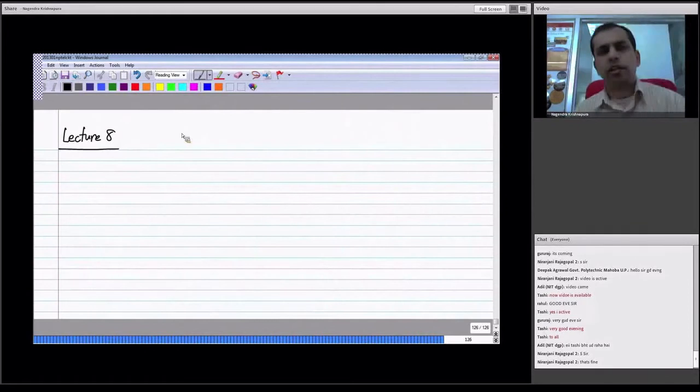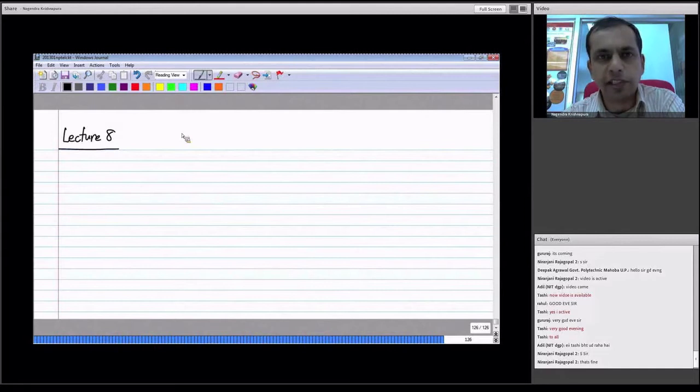This is lecture 8. In the previous lecture, we looked at nodal analysis, how to do nodal analysis when you have a circuit with current sources and resistors. That was the easiest case. And we extended that to when we have voltage sources. In that case, if you are doing hand analysis, you can use a super node. If you are trying to set up the equations for a computer, you can set the current through the voltage source as an extra variable and go ahead with the analysis.